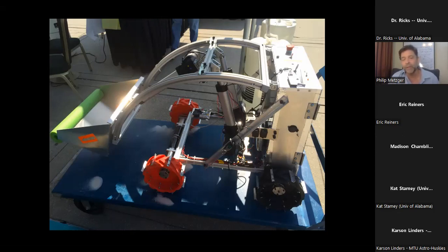Now, there are some ways to avoid that. One way to avoid it is simply to have a lot of traction so you can drive on the remaining two wheels. The other way is a lot of torque and gearing way down so your wheels turn slowly with huge power. Another way is to have some sort of mechanical or electronic linkage between the front and rear wheels so that the rear wheels cannot spin at a higher rate than the front wheels and vice versa.